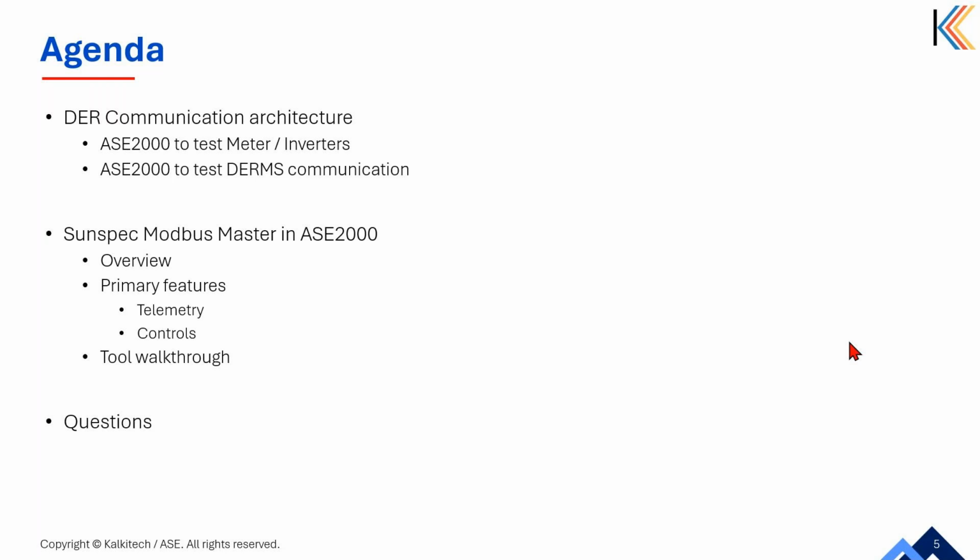But in the case of SCADA, as you know, it's mostly RTUs communicating to the SCADA locally, and SCADA in the local station has many capabilities to provide interfaces to the operator and to issue controls. That site level or station level function or human intervention is not expected in DER systems. In most cases, it's like a control center in the SCADA world. DERMS acts like a central system where it monitors multiple sites and sends controls to multiple sites to manage the entire system.